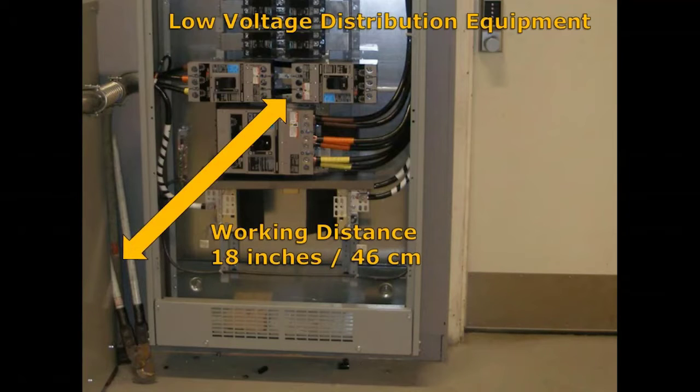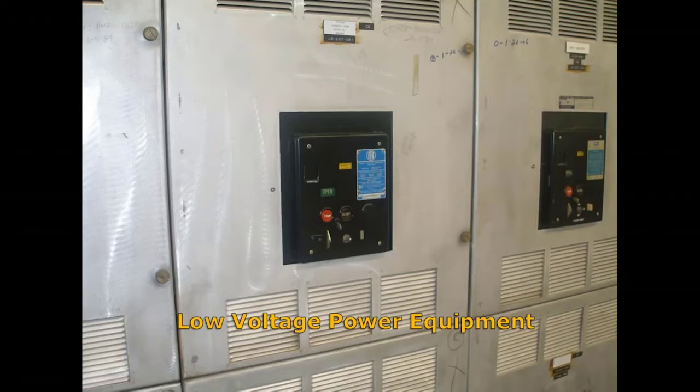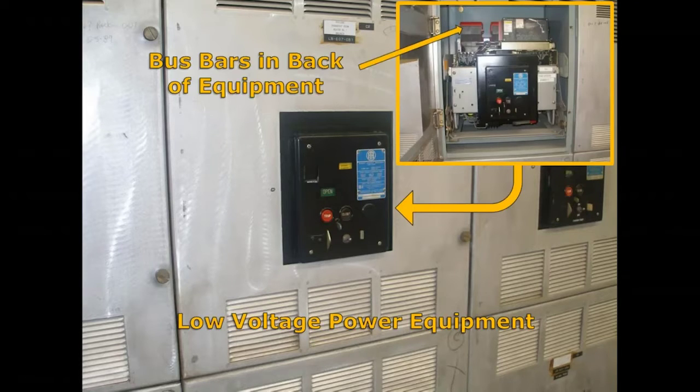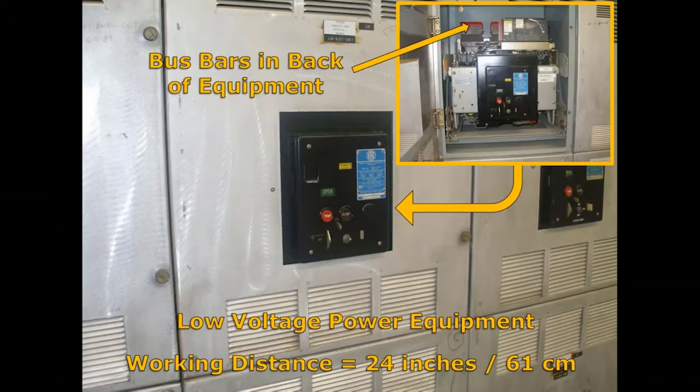Now, do you have to use 18 inches? No. You could use maybe what's suitable for you. There are limitations on how close it can be within IEEE 1584. But 18 inches, that's what most people are going to use because they can point to a standard and reference it. If it happens to be low voltage power equipment, then the IEEE 1584 standard says, well, you can use 24 inches. And the 24 inches is actually considering that the energized parts are a little bit further back into the cubicle. Again, do you have to use 24 inches? No. Some people will use 18 inches to be a little bit conservative.